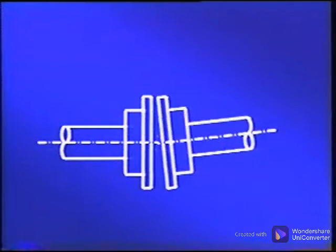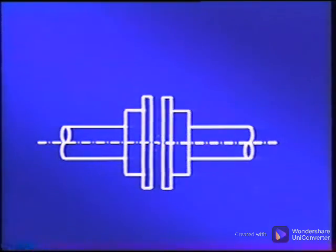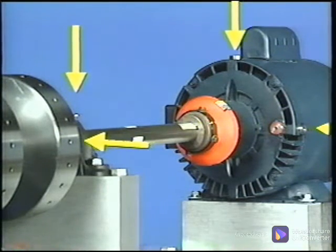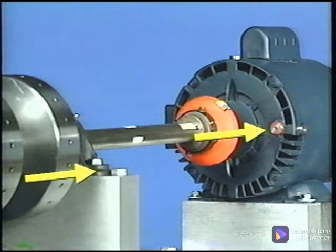When a shaft is bent at the coupling end, it moves in the same way as a combination of angular and offset misalignment condition. The phase data will have a 180-degree change across the coupling in vertical to vertical or horizontal to horizontal measurements. The axial measurements across the coupling may have any phase relationship depending on the coupling type and the amount the shaft is bent.